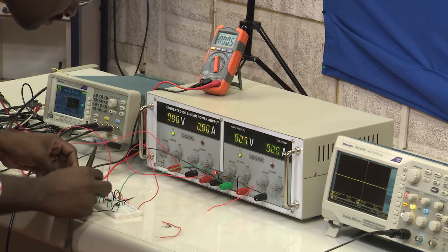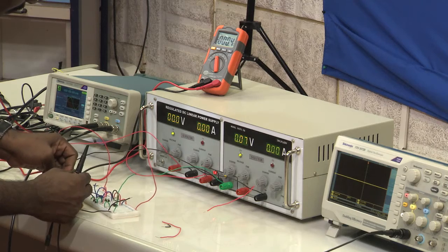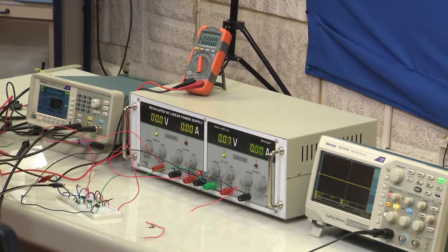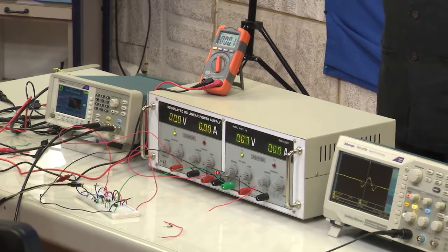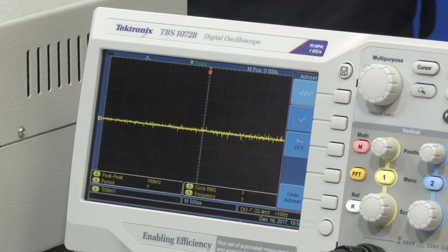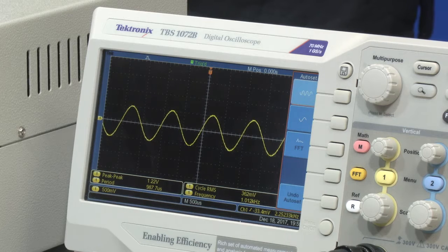All right, and now he has to check 1 volt in channel 2, the 1 volt that we are applying to channel 2. So, again he will take a probe from the function generator and connect it to the oscilloscope to check whether it is 1 volt peak to peak. He has to check it on the oscilloscope. If you see, it is 1.04 volt peak to peak, alright.